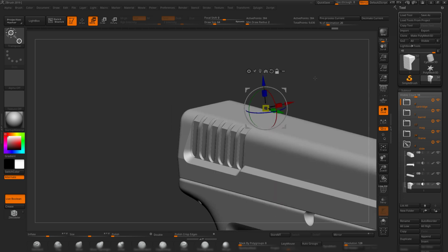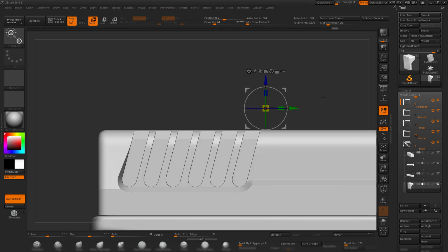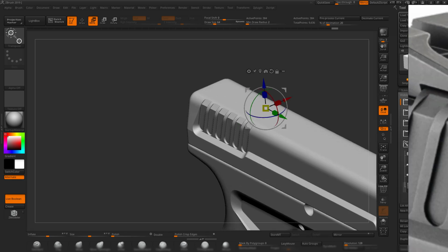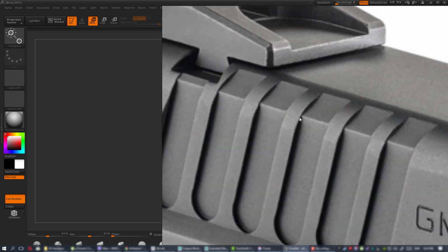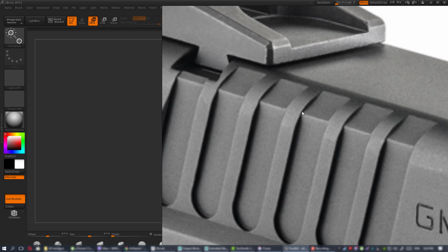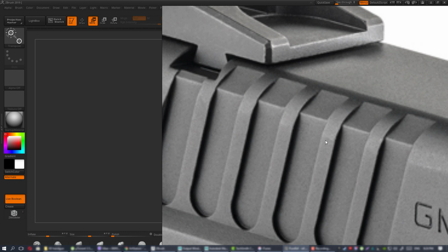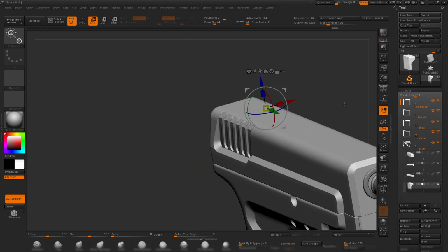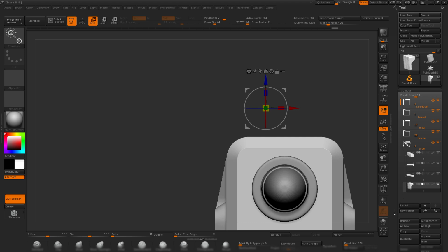Well, this part here is quite difficult in terms of future low poly modeling and baking, because in real life you can see that this angle almost touches this surface right at this point, but when I'm going to bake normal maps, this place might be too thin to represent any kind of normal mapping, and it might look bad, and I would take the risk and make this part a bit more separate from each other.